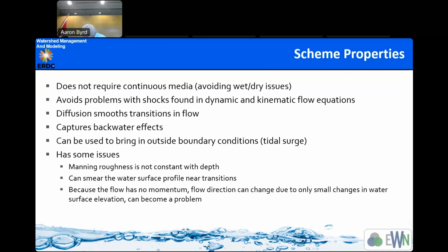Does that happen typically? No, it's usually a problem where it's very flat. When it's very flat, because you think about it, it is almost a completely flat water surface, and maybe over here it's a millimeter higher than here, and then it flows over here and brings it up 2 millimeters. Well, now it's higher over here, and it flows here. And so normally it'll just sit there and wiggle, but it can start to go negative and it crashes. So that's an issue with diffusive wave, the biggest problem with it, I would say.